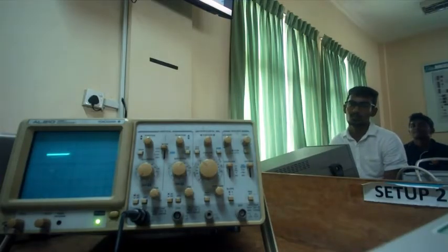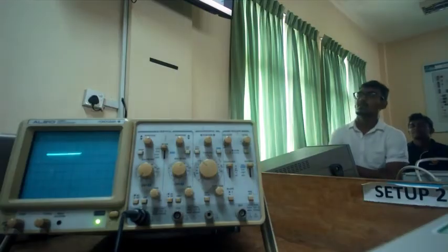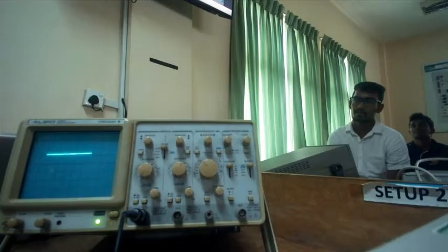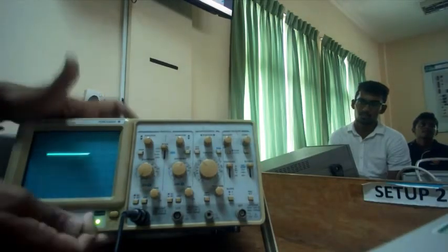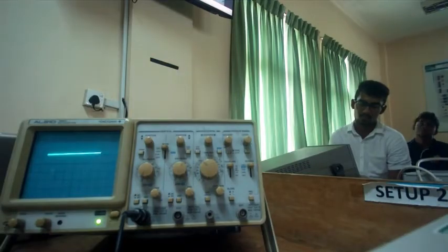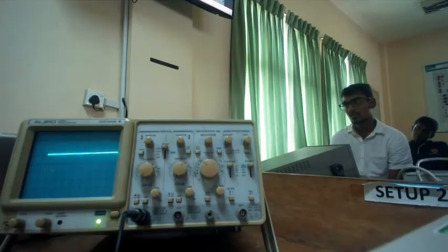But in addition, unfortunately, where does this 1 meg come from? 1 meg is not physically there. It's the input impedance of this device. My oscilloscope, I said I have this thing, it's connected. Between this pin and this, these two, this is connected to the chassis. Between this and that, what you have is an impedance. It can be modeled as this.